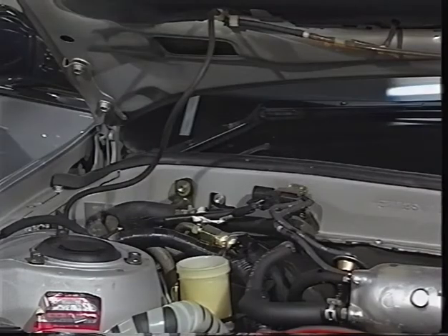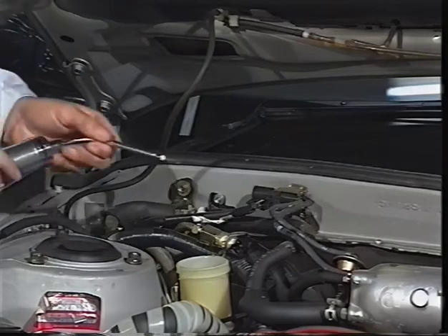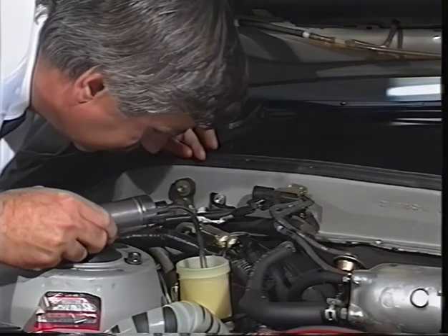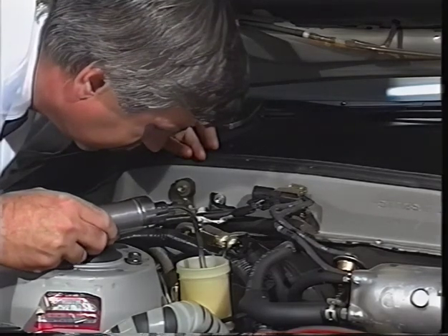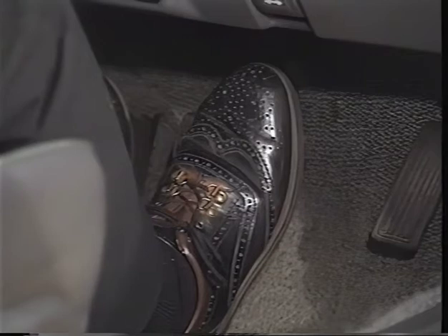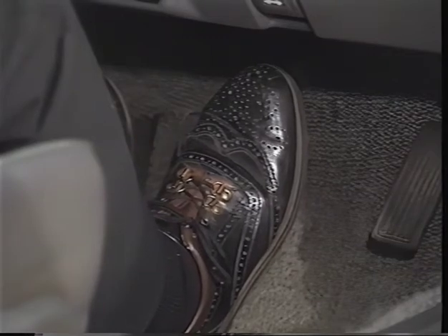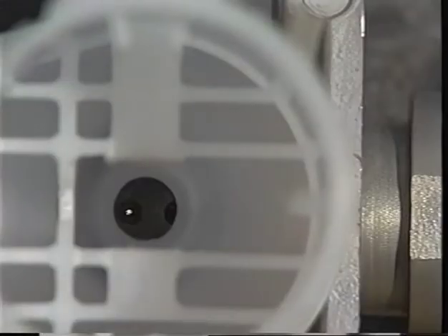However, in the absence of one of these gauges, it may be possible on non-fast fill master cylinders to drain the primary reservoir. Shine a light down the primary compensating port and have an assistant note the distance the pedal is depressed before the primary cup is seen crossing the compensating port.